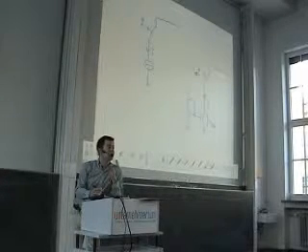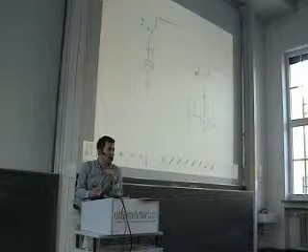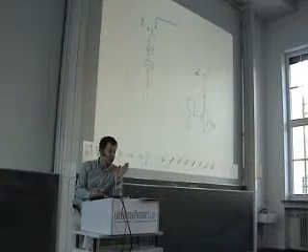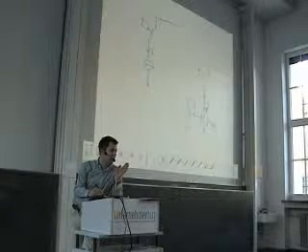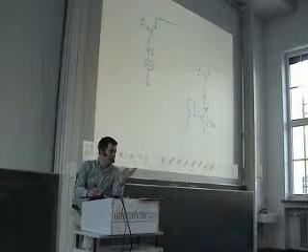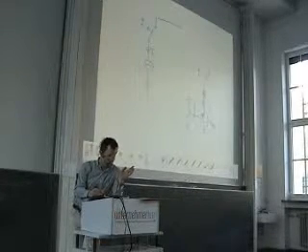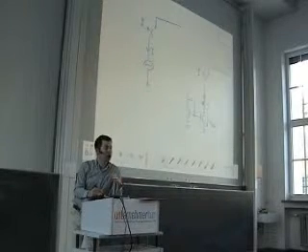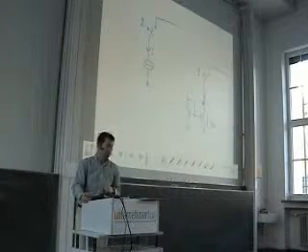So there's only a small amount of time while I switch from one node to the other one where the current cannot flow. And during that time, this voltage cannot drop completely. So I switch fast, then the current can continue to flow. The potential at this node does not change. And if I switch it back, I can provide this current immediately and have a fast settling.